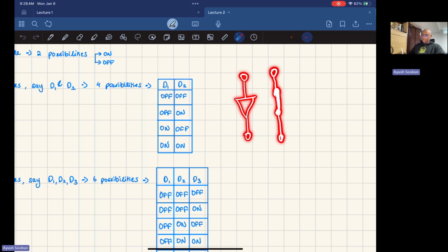And if it is on, that means current flows in this direction, correct? But now let's say you assume that diode is on, it's a short circuit, you're supposed to have a current flowing down in the direction of that triangle. However, when you did your analysis, it says that the current value is negative. That means the current is actually flowing in this direction.